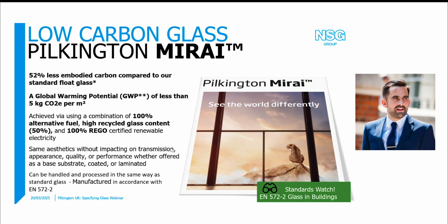As I mentioned earlier on, this is just the way the glass is manufactured. The glass itself is exactly the same aesthetically. There's no impact on the transmission, the clarity, the quality of the glass. So it can be coated with solar control coatings and all the coatings necessary. It can be laminated, etc. So you can work with it in exactly the same way. And yeah, manufactured in accordance with EN 572, which is the basic soda lime silicate glass production standard.